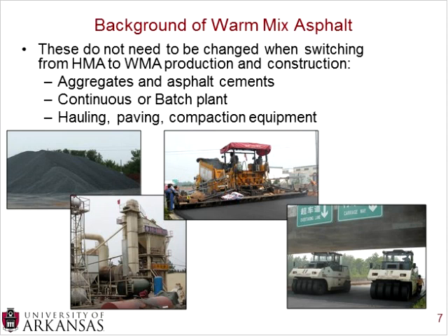But all in all, you can use the same equipment for that. And also then on the job site, you can use the same hauling, paving, and compaction equipment as well. So warm mix asphalt usually does something different with the material side of things, and it's usually adding something new. So pretty much everything else you can keep the same.